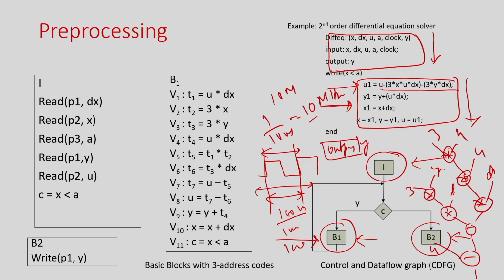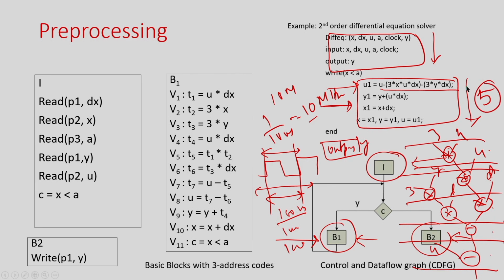So the first thing that comes to mind, once I have the behavior, is to decide how many clocks to distribute the operations into, and then I can execute the operations in, say, 4 clocks. For example, given this behavior, I decide to do these 2 multipliers at a time, these 2 multipliers at a time, and then this and this. So 1, 2, 3, 4, 5. Say in 5 clocks I want to do this. If I do this in 5 clocks, my clock period will be 5 times smaller and my clock will be 5 times faster, right.